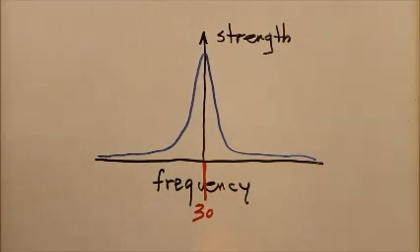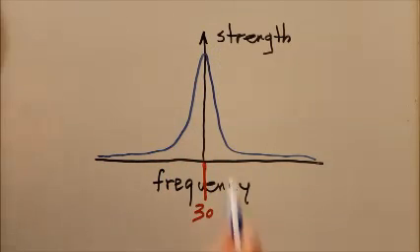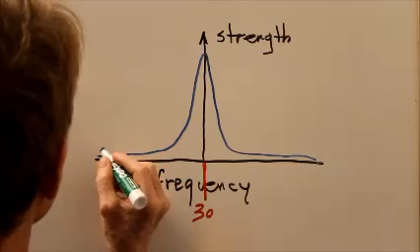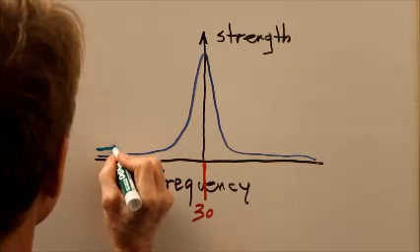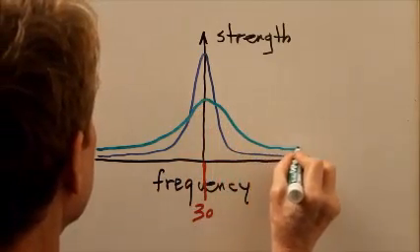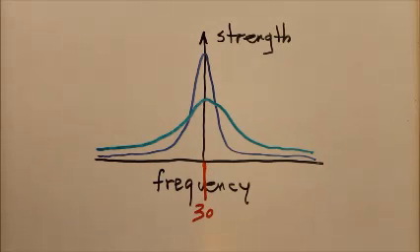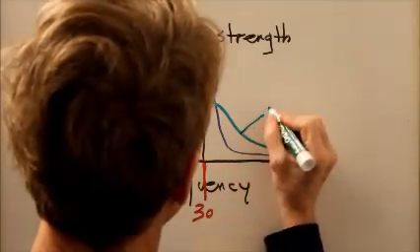The circuit will not pass very much signal energy until we get very close to the resonant frequency, and of course the best signal passage through the circuit will occur at the resonant frequency. Now we change the resistance to 40 ohms. We're going to see that it's still resonant at 30 megahertz, but it's a lot shallower of a response. At the resonant frequency, it won't pass quite as much signal because there's more resistance in there that creates more loss. This is with the 40 ohm resistor,